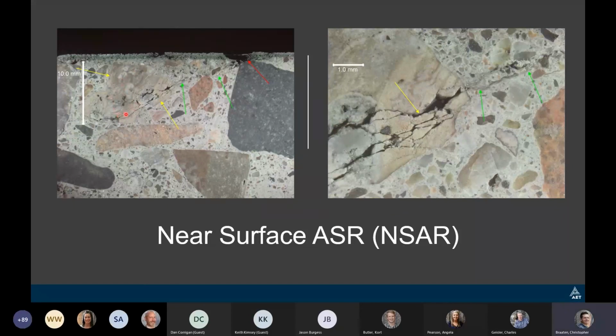I should mention that in petrography, when I'm doing the initial C295 analysis, I say potential alkali silica reactivity, because it might not react. You might see the textures, but it might not ever react. It might have used a lower alkali cement, or there might not be moisture around to create the reaction. But this one had the constituents within the rock.